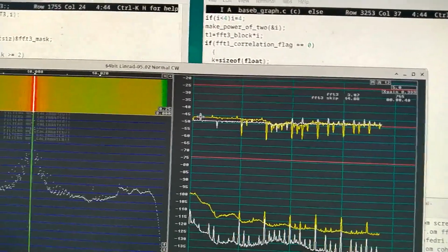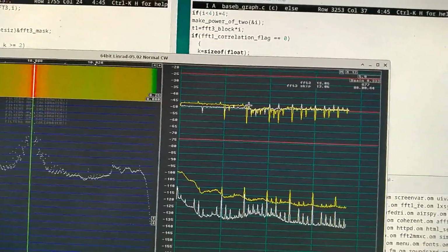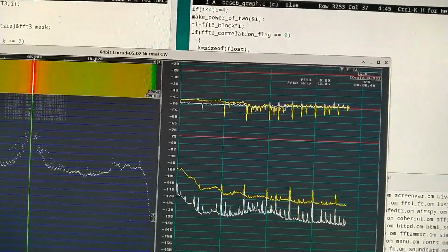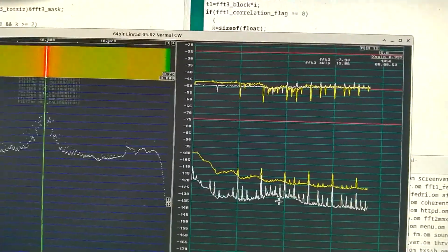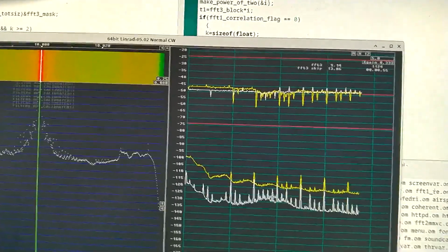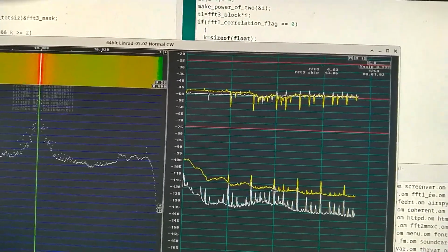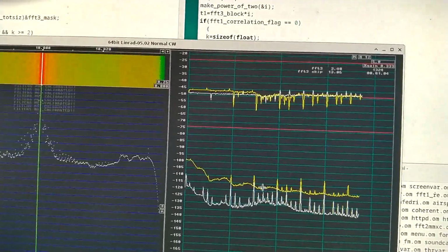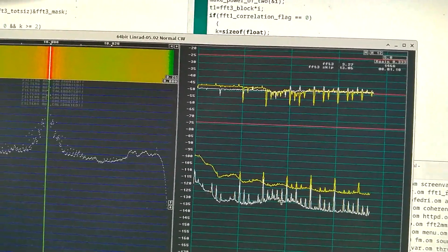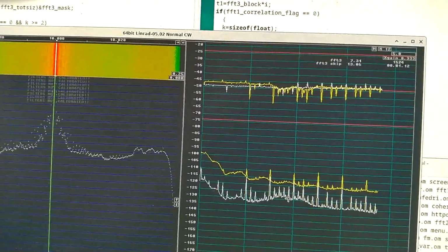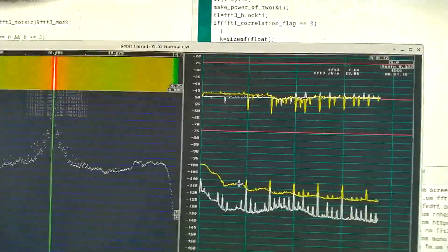There is a correlation at low frequencies up to about 3 kHz. There something happens. There is a filter involved somehow. And we can see, of course, also that the amplitude modulation varies like this. And the phase modulation has a similar behavior. Although it seems to be phase shifted, it has a maximum here, close to where the AM modulation has a minimum. Well, not quite, because here is a maximum and also there is a maximum.